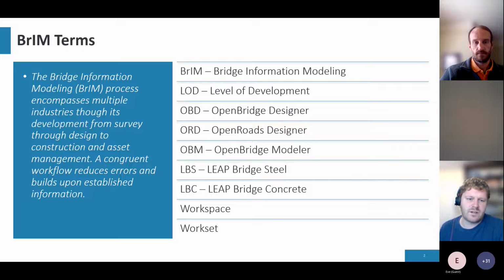They are incorporated in Open Bridge Designer. That's LBS and LBC. Workspace is the configuration that you set up to pull from for all of the model elements. A work set is a subset of the workspace that you can set up specifically for projects. I'll get into that more as I get into configuration setup.